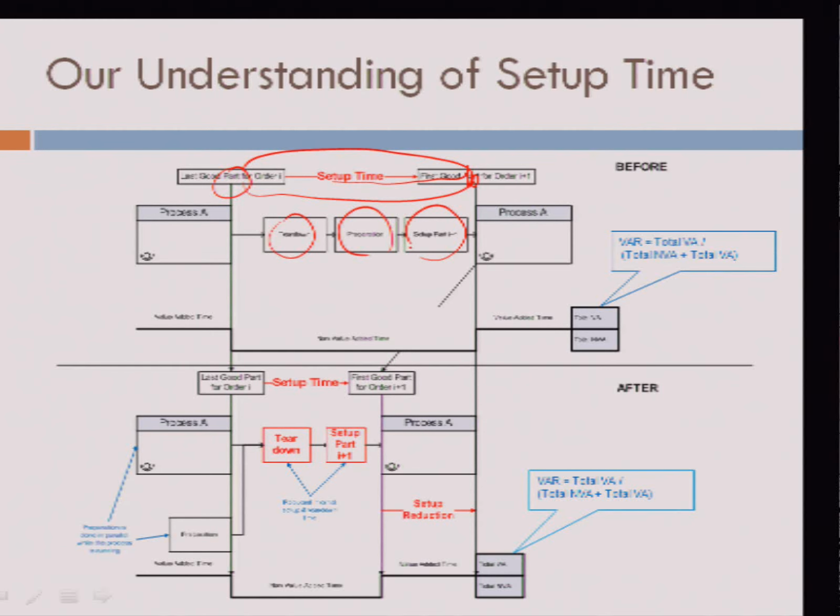So that is typically the total setup time. And then of course we can look at those activities which have to be done, we call them internal activities, and then we look at non-value adding activities, and appropriately we can look at setup time as having its own value stream, and then we can compute a value added ratio even for setup, meaning that for the total setup cycle, there's so much time which absolutely is time that you have to spend in setup, divided by the total time it took to perform the setup, and the more that ratio hits 1, the better you are at quick changeover.